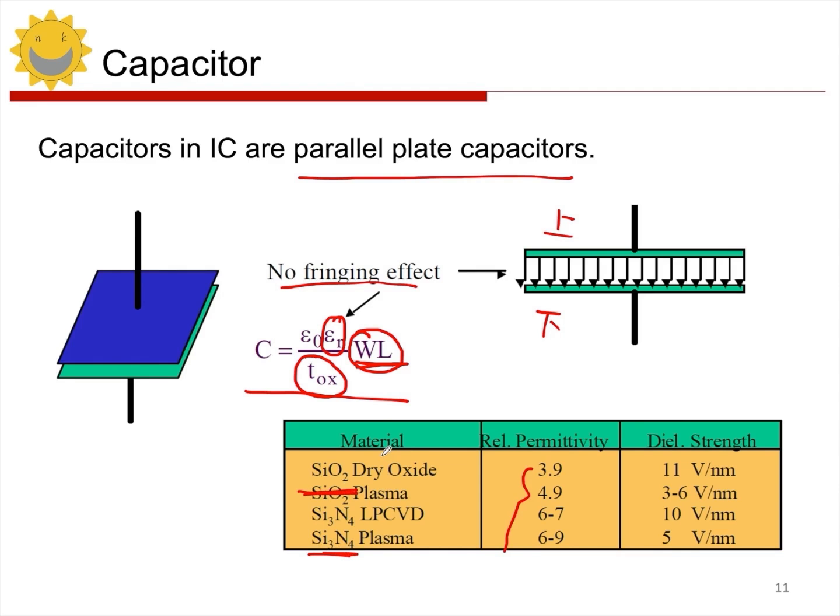So for the designer, what can be changed? There are actually two aspects that can be changed. One is the thickness of the oxide insulating layer, and the other is the area of the metal plate, right? Let's take a look at the thickness. You can't change the thickness flexibly. Of course, you can choose. Generally speaking, a process will provide different thicknesses so you can modify it. But once it is set, it basically won't change.